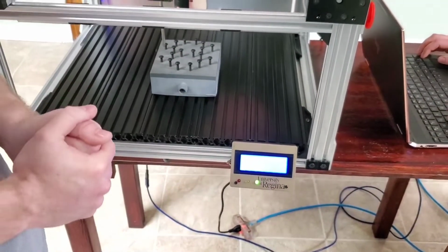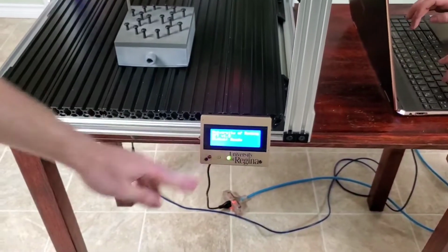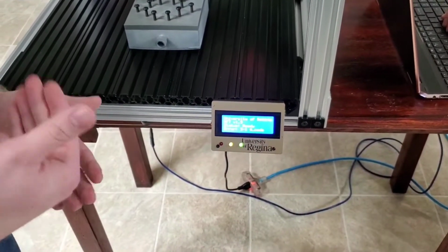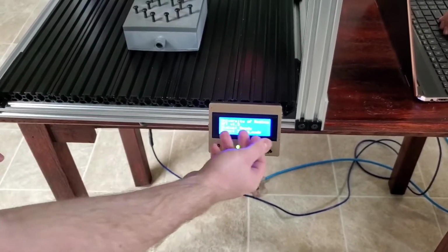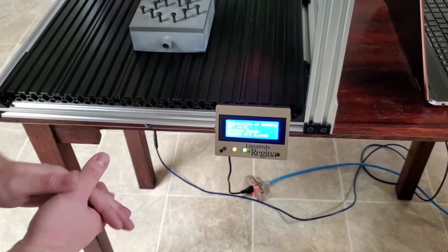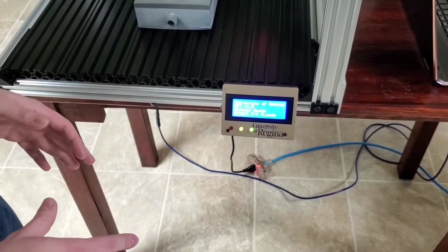Now we're going to do a few different errors. So Matt's going to send it a bad G-code. And we're going to see here a G-code error. So we have 3-1. So that's 3 means it's non-critical. 2 is also non-critical. And 1 is just the first error code in that situation with a nice description for the users. As you can see, the yellow or orangish LED has lit up, indicating it's non-fatal, and we don't need a reset at this time.